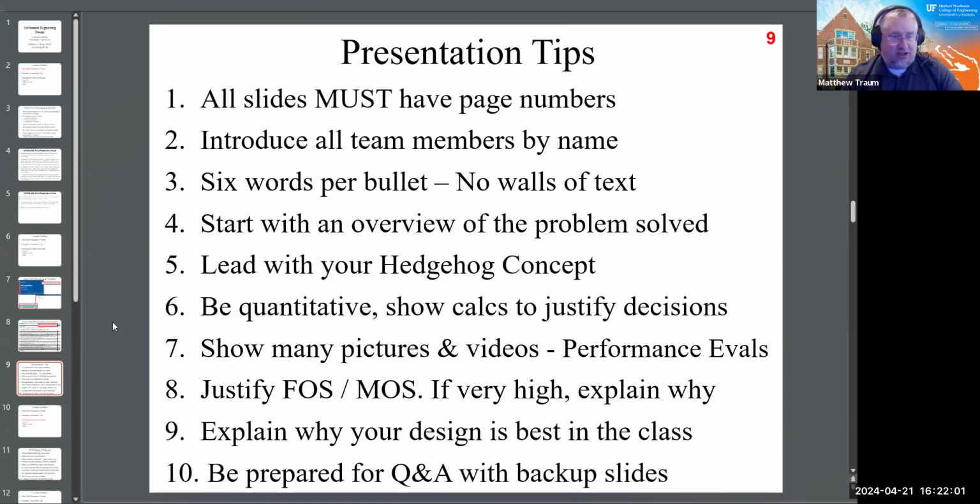So please justify your factors of safety before you give them. Explain why you selected a particular value. Don't just say, oh, it was 1.7 and I don't know why. You actually have to explain why. Some of our panelists think in factor of safety, some of them think in margin of safety based on what industry they're from. So my suggestion is to use both numbers. They're basically just 2 different ways of communicating the same information. So just use them both and just be aware that you have a diverse audience that comes from a variety of different industries.